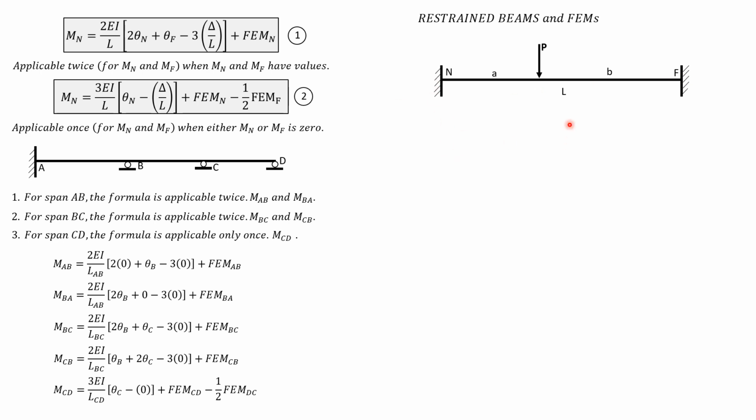And the second equation is EI times the deviation of N relative to the tangent at F. Because the tangent at F is horizontal, it crosses N. So therefore, the vertical deviation of N relative to the tangent at F is 0.